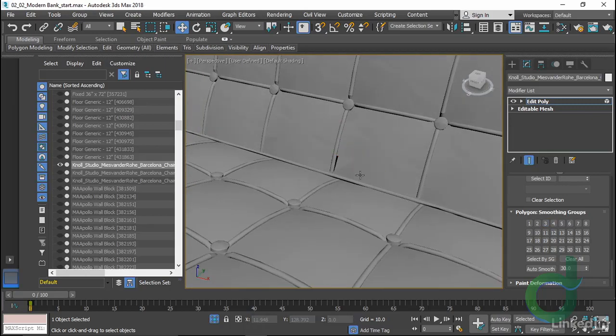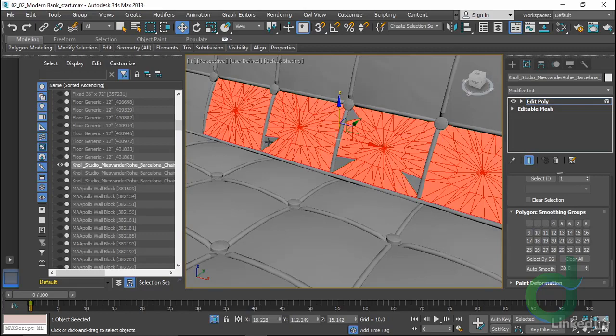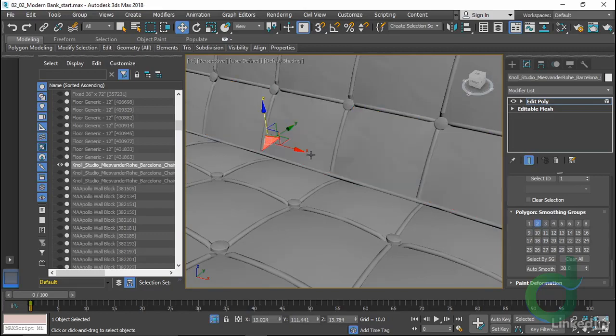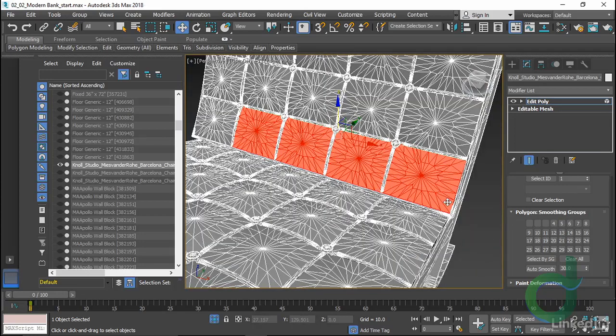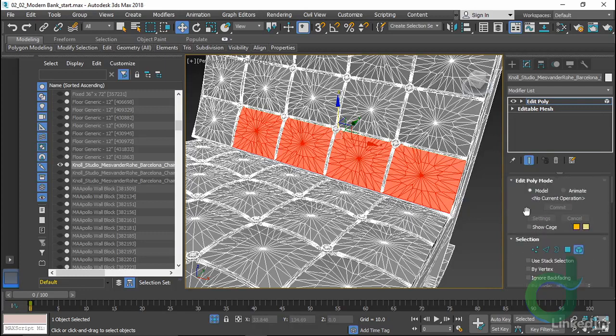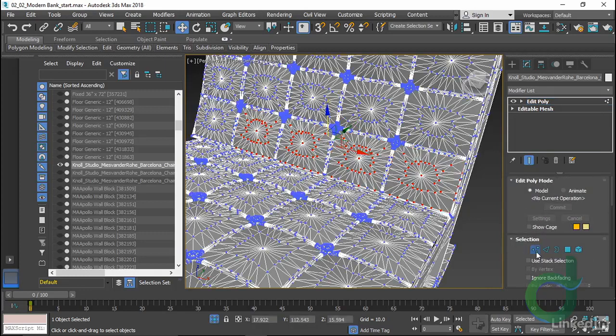That one was not an extra. So what I need to do is go through here carefully and see what happened in that import. Again, not an extra. I'll weld these together then, picking these polygons, converting the selection to vertices by pressing Ctrl while clicking on the vertex button, and then welding the selected vertices.